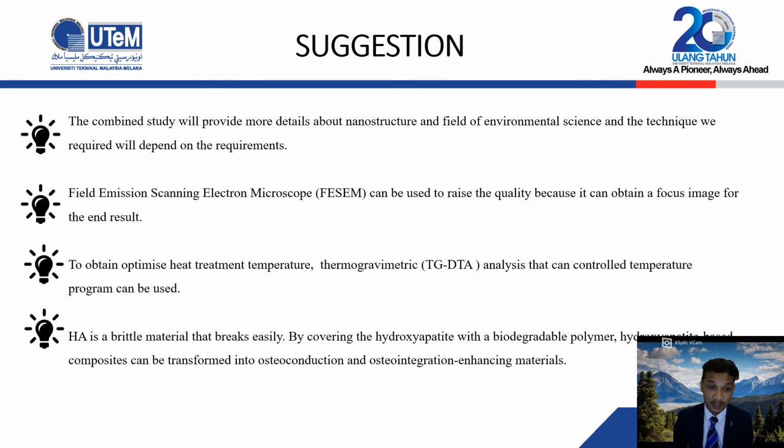Third, to obtain the optimal heat treatment temperature, TGA analysis that can control the temperature program can be used. Lastly, HA is a brittle material that breaks easily. By covering the hydroxyapatite with a biodegradable polymer, a hydroxyapatite-based composite can be transformed into osteoconduction and osteointegration enhancing materials.